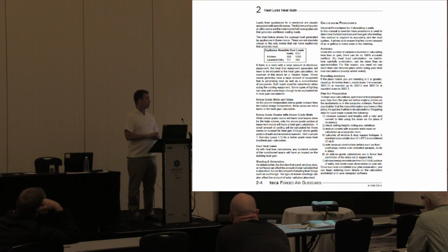The other thing is we don't count people in the heat loss. Because people give off heat, we don't count the appliances in the heat loss. We don't count computers in the heat loss. We don't count your big monster TV in the heat loss that's putting off heat, all those other things. That's just all things that will add into the house. If you have a situation where you're adding a lot of stuff, then you can take it into consideration. But when you sell the house and the new person moves in and they don't have all those things, then you're still going to want the same size furnace or system in the house to make sure it'll maintain it without those options. It just means they won't run as much.